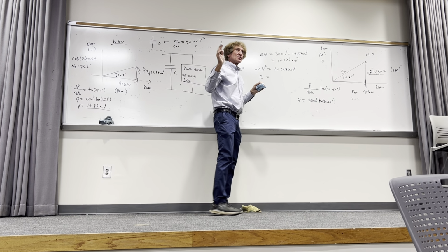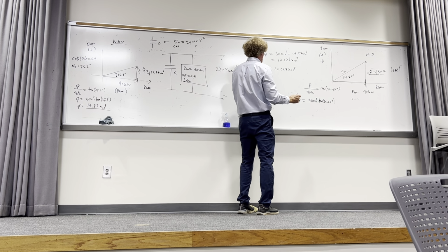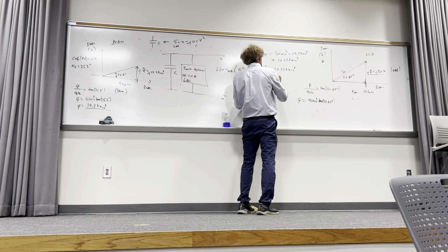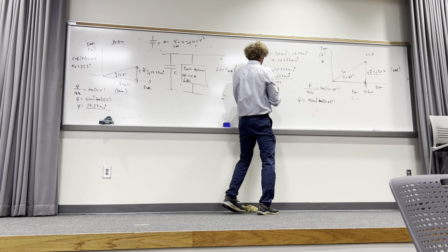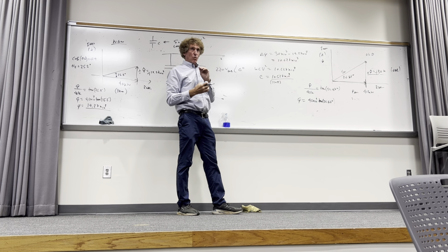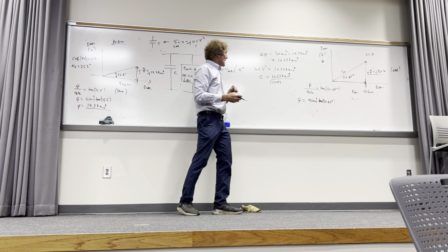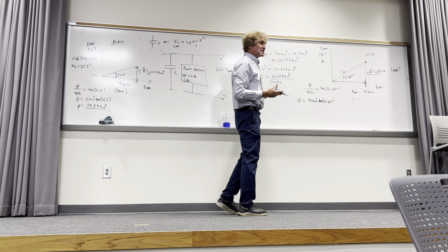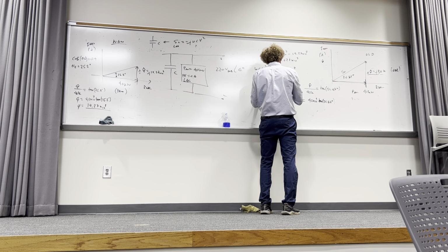This is at 60 hertz, am I correct? Is it say 60? Okay. So it's equal to 10.627 times 10 to the third. Then it's divided by 120 pi. The 120 pi is omega, or 2 pi times 60. That's all that is. You with me? Then I have to divide by V squared. Now the voltage is 220, and I have to square it.